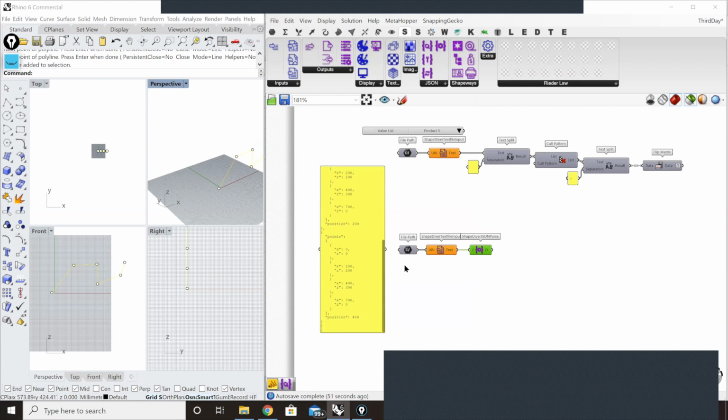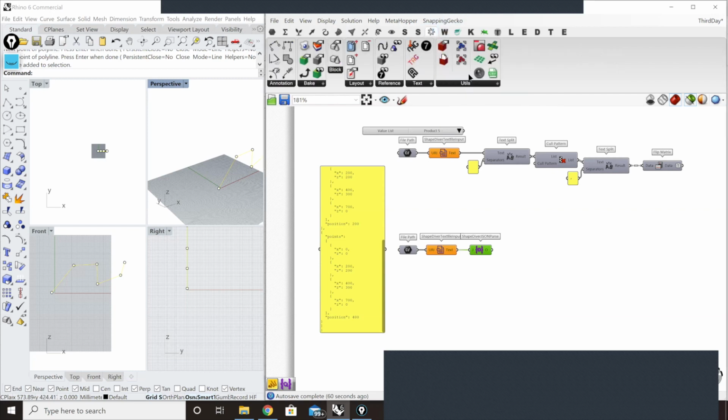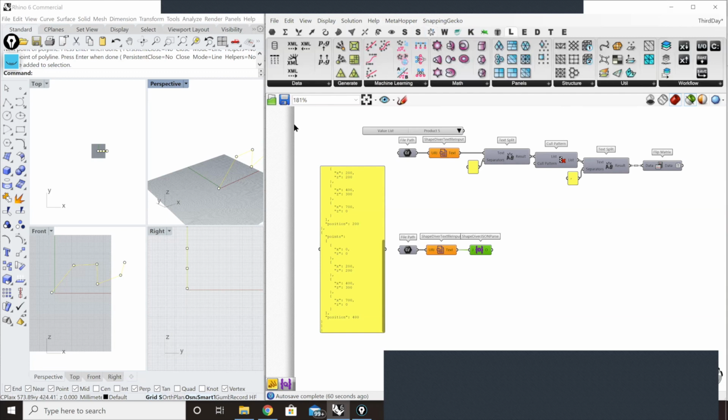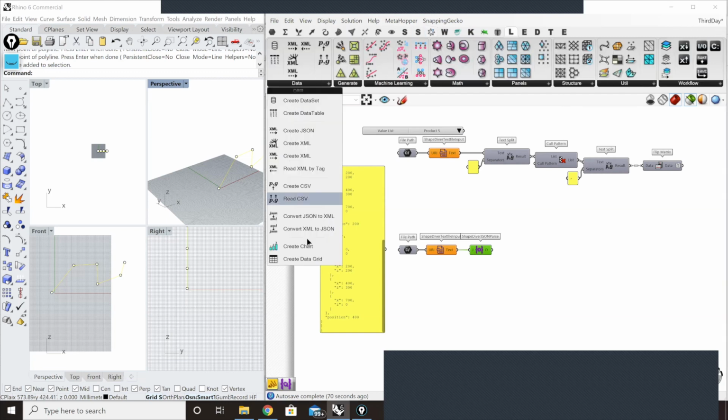And XML files actually are also convenient, and you have tools to process them in a plugin we support on ShapeDiver, which is Lunchbox, I think. Lunchbox or FabTools, I always confuse which one is what. I think it's Lunchbox. You have XML processing tools, so you can extract information from XML. So those are all convenient ways to import and export data, and manipulate it inside Grasshopper.